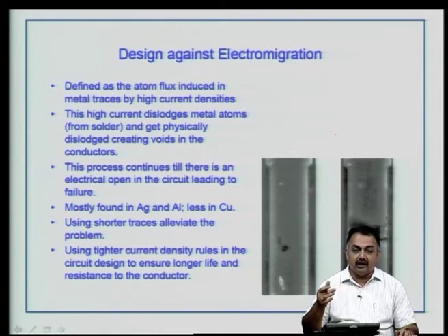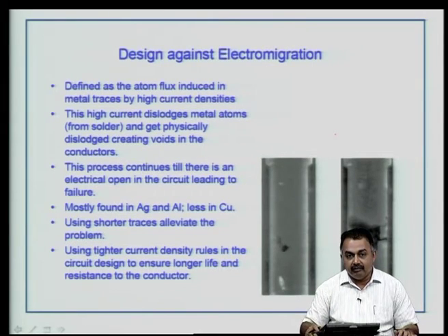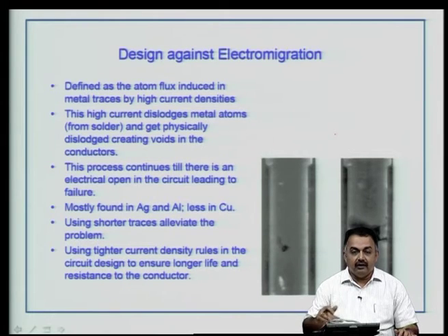The different current densities that you are using, the kind of moisture levels, the kind of external debris and process debris if they are there, can make a situation where you can have disturbances in the copper in terms of voids or creating what is known as whiskers in tracks, which can lead to a short due to electromigration, but this is a slow process.